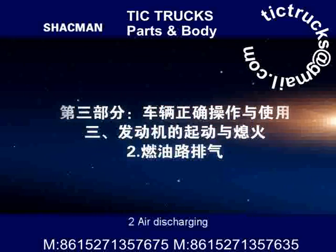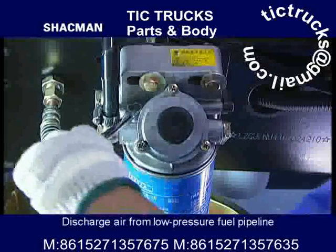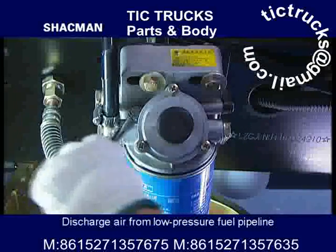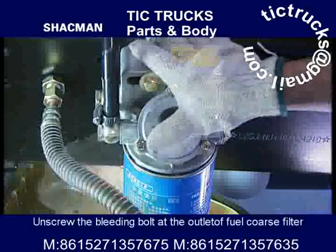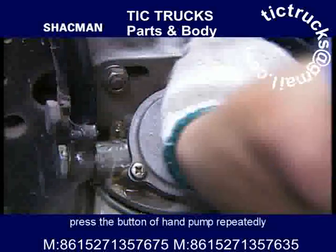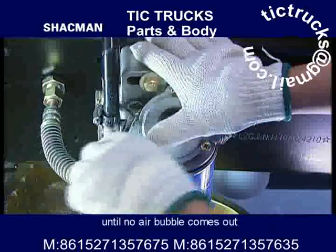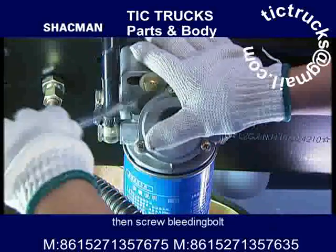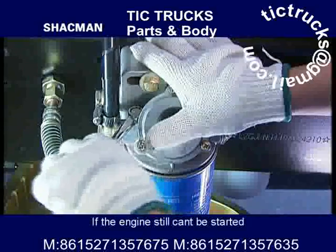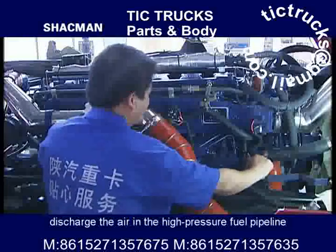2. Air discharging. The method to discharge air is as follows. Discharge air from low-pressure fuel pipeline. Unscrew the bleeding bolt at the outlet of fuel coarse filter. Press the button of hand pump repeatedly until no air bubbles come out. Then screw the bleeding bolt. If the engine still can't be started, discharge the air in the high-pressure fuel pipeline.